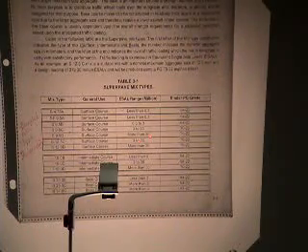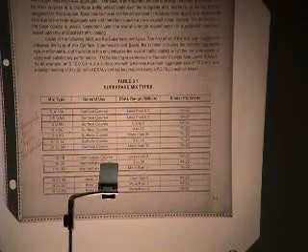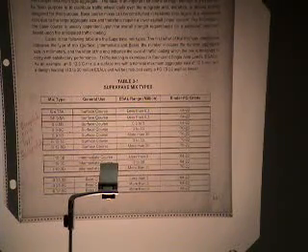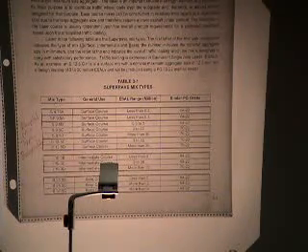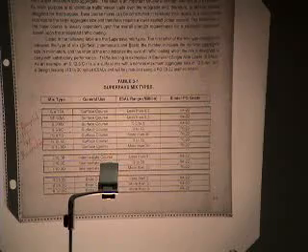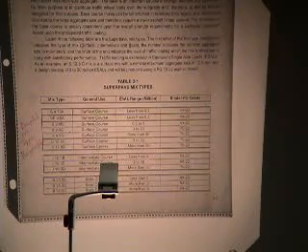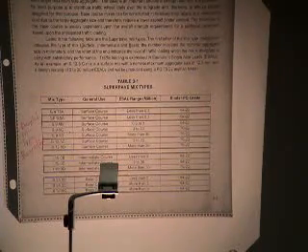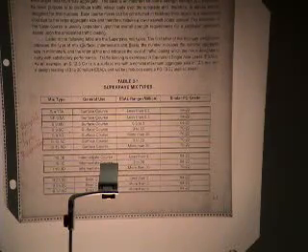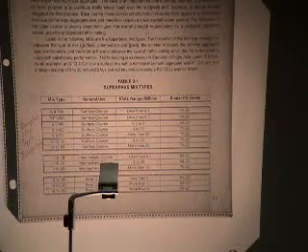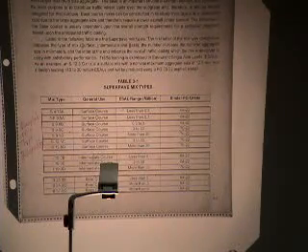And again, it's related to this column, what is called an ESAL range. Now, what is ESAL? E-S-A-L stands for equivalent single axle loads. It's a way that pavement management people who design pavements convert the traffic information to a number that they use in their design process.